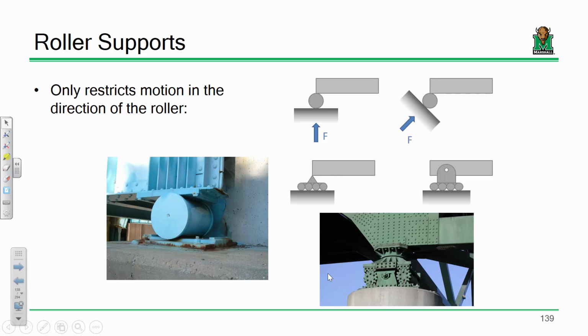And the difference is, you have the bridge and you have a plate that connects it to the abutment in the ground. Fixed bearings just have a hole in the plate, whereas with expansion bearings, the hole is sort of like a slotted hole. So the bridge can move along the axis a bit. And the reason we do that is because of temperature. Over the design life of that bridge, the girder will get hot and get cold and it'll want to expand and contract. So we actually want to allow it to move a little bit.